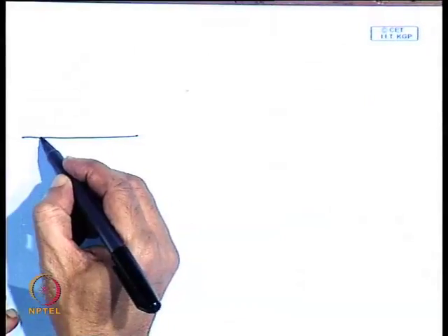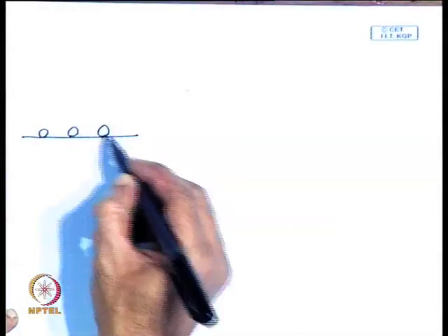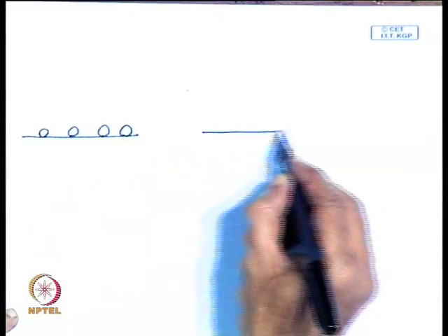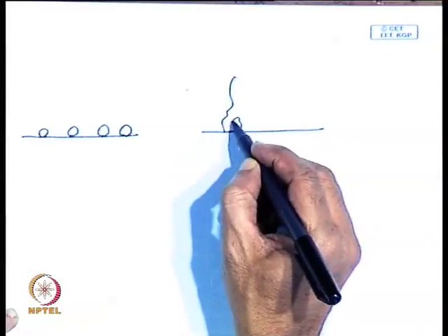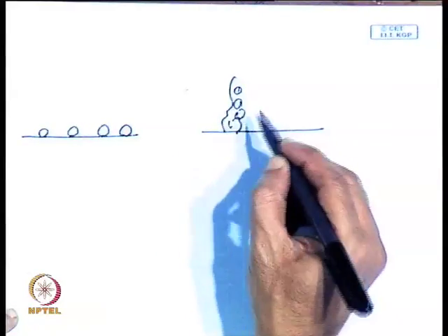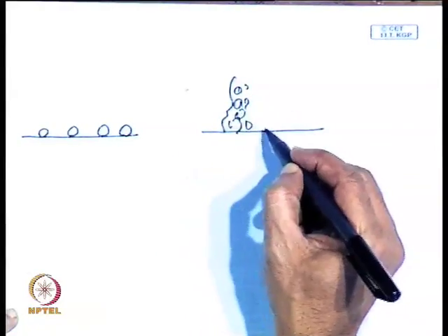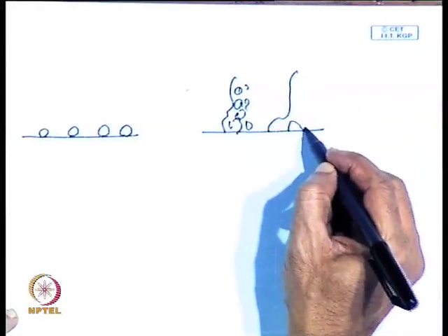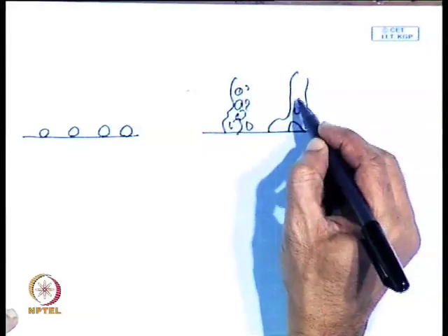Now, one thing would be appreciated by you, that out of different regimes of boiling, in nucleate boiling we have seen there are regimes of isolated bubbles. Then there are regimes of jets and columns, which are actually due to mergers of bubbles.